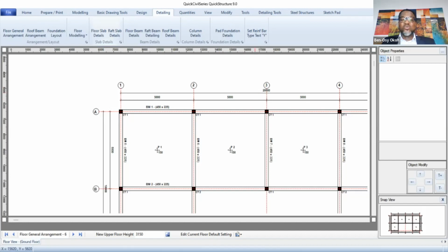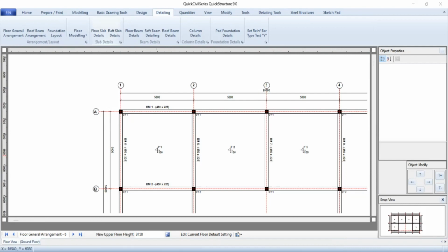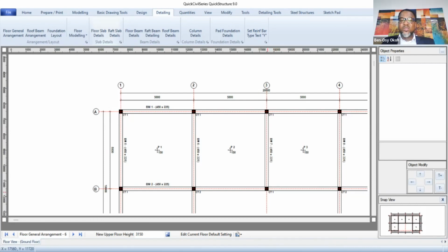And now you begin to look at some of the decisions you have to take. What if I break it with a column? The column will reduce the depth of the beam from maybe 750 or 800 to 450. Reduce the reinforcement. Okay, what of the concrete or the reinforcement of the column, the base of the column?